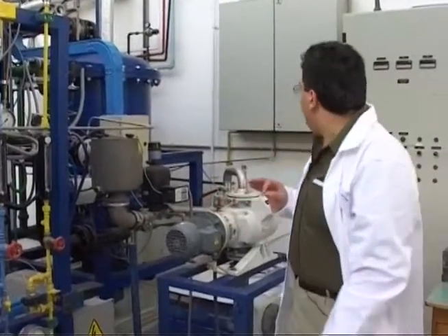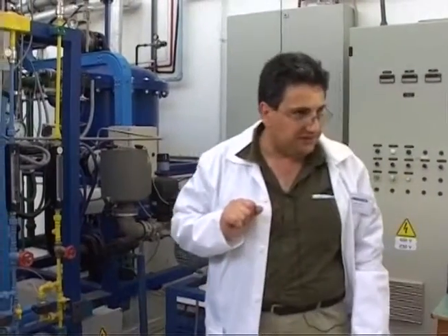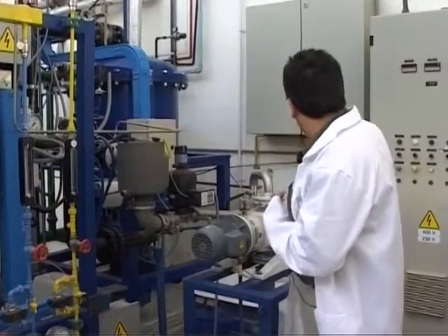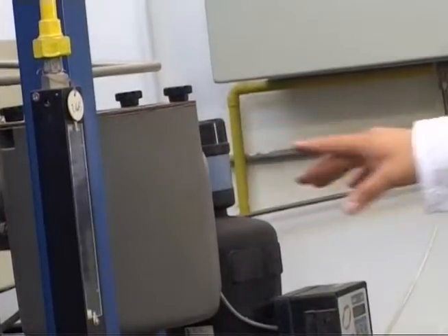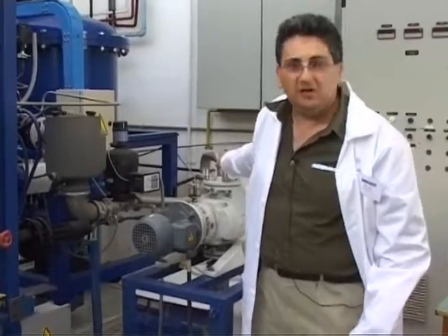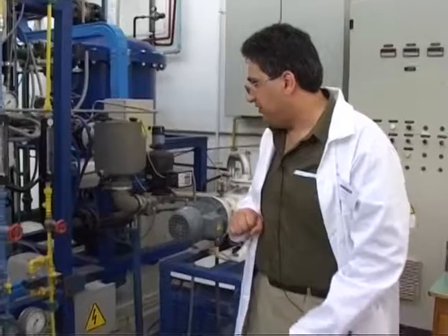In the case of plasma nitriding, a tiny amount of nitrogen is introduced through a series of leak valves and hydrogen to achieve the required pressure. The pressure is monitored by controlling the flow rate of the gases and by using a metering valve which throttles the input of the vacuum pump, thereby controlling the pressure inside the furnace. It is important to keep the pressure constant because the pressure controls both the ion energy and the plasma power.